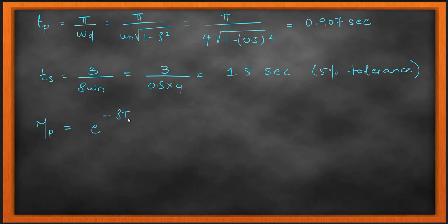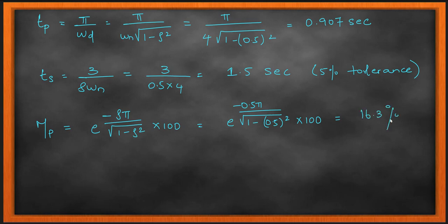But to set these values, so what is my rise time of the system, how long it takes to reach a 300 mile per hour maximum speed, in 10 seconds. Okay, I bring it down to 5. I can bring it down to 5 by just adjusting this zeta and omega n. I'm just saying it is an example, but there are a lot more things to that. But here I can tell that much from my graph, and I'm writing this time response also for you. Thank you.